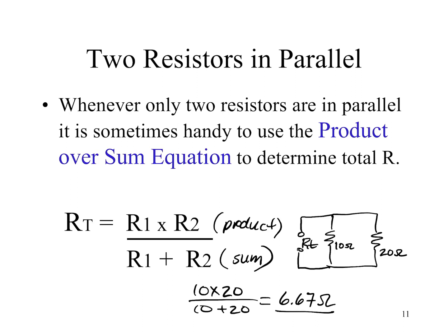And notice how the total resistance is less than the smallest, which was 10 ohms. What would that mean if we were actually looking at 3 resistors and we had 30 ohms in parallel yet still here to consider? Well, it doesn't mean with product over sum that we're out of luck when it comes to 3, because what it means is we can look at the parallel resistance that we determined for these 2 resistors as that equivalent value, and now just use product over sum once again.